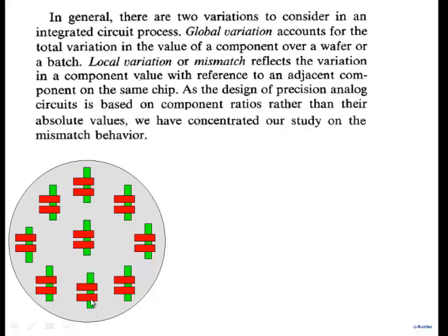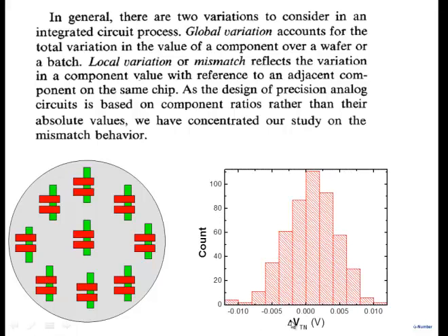So I make M1, M2 here. I make M1, M2 here. I make here all over the place. Suppose I fill it up with two transistors here, right? Now I'm making them very close. I expect threshold voltages to be same, right? Exactly same process, everything same. Now suppose I measure of this transistor VT1 and this transistor VT2, and I take the difference, and we call it as delta VT.